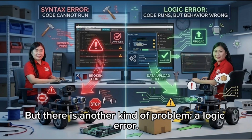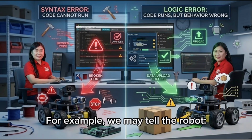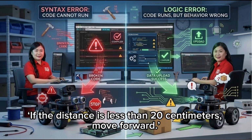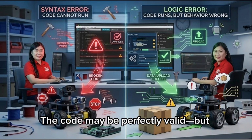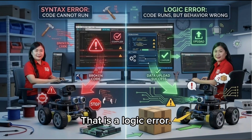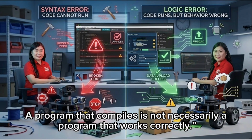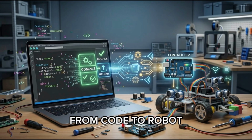But there is another kind of problem, a logic error. The program may compile successfully, but the robot does the wrong thing. For example, we may tell the robot, if the distance is less than 20 centimeters, move forward. The code may be perfectly valid, but our intended behavior was for the robot to stop. That is a logic error. And this is an important lesson in robotics. A program that compiles is not necessarily a program that works correctly.